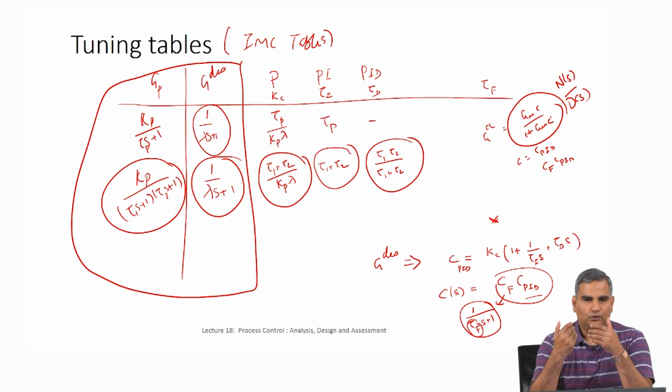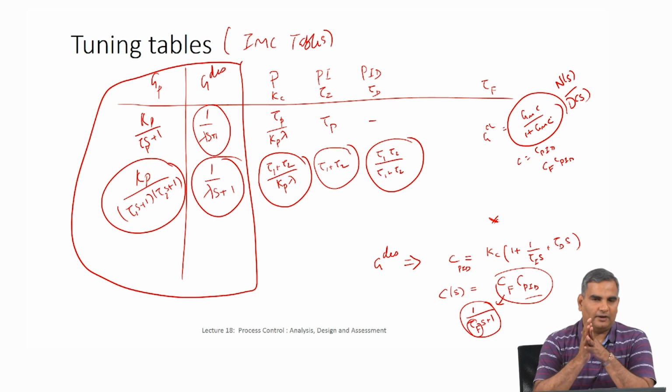And then we also took the same state space equations and multiplied by e power minus st and showed you the Laplace transform, and showed you how the differential equation state space models get converted into algebraic equations. And once we have these algebraic equations in Laplace domain, we showed how the convolution solution in time domain becomes simply a multiplication solution in Laplace domain.